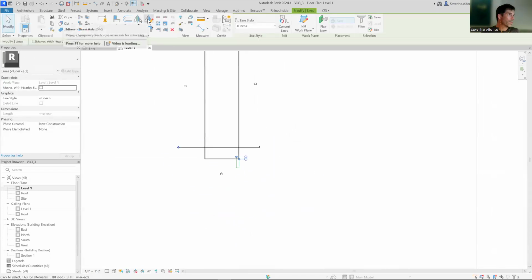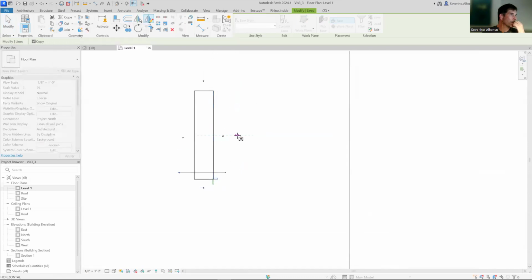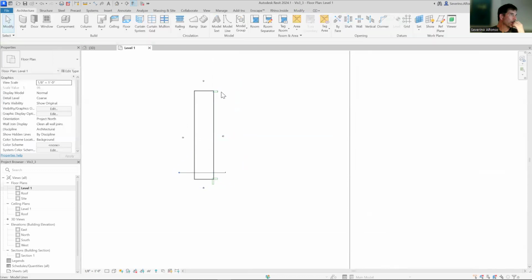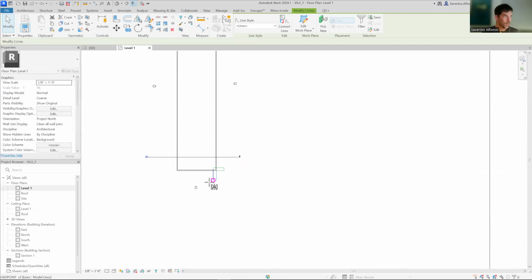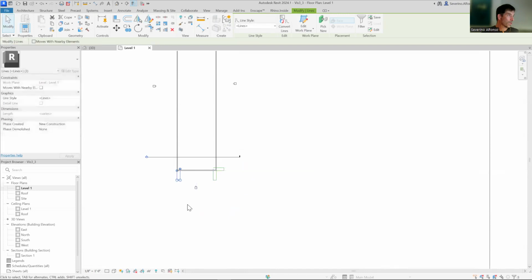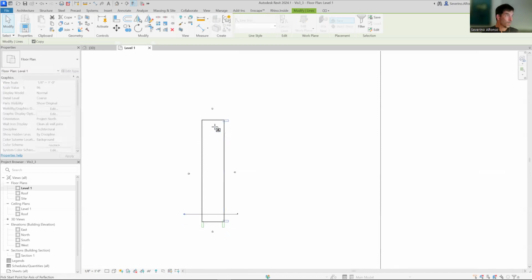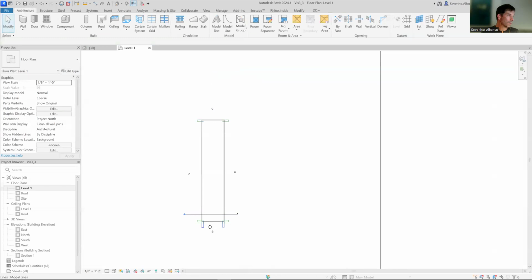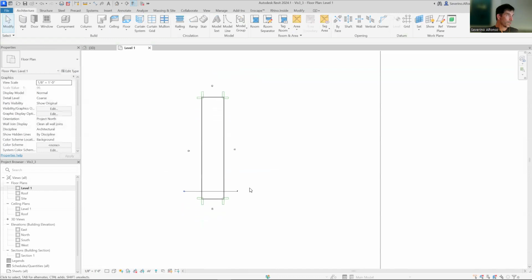There's a particular mirror option. There are 2 of them. One of them is drawing the line. The other one is picking the line. So I'm going to select DM shortcut and go to the middle point. And that copies the option here. I'm going to select this one, DM as well again. Go to the middle point, copies, and now I'm going to select by pressing Control both of these, DM, and selecting these 2, DM. Okay, so it's copying everything a little bit.